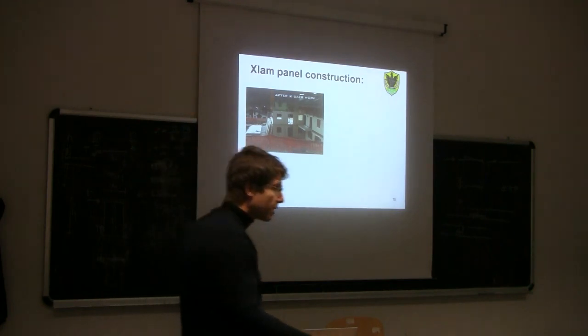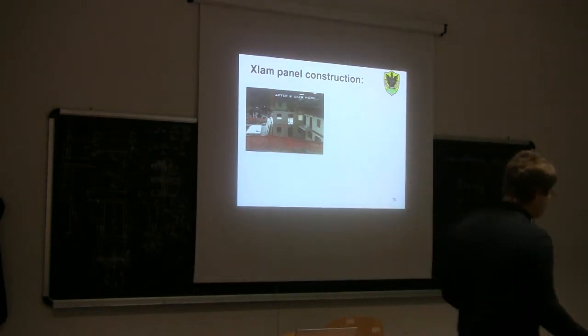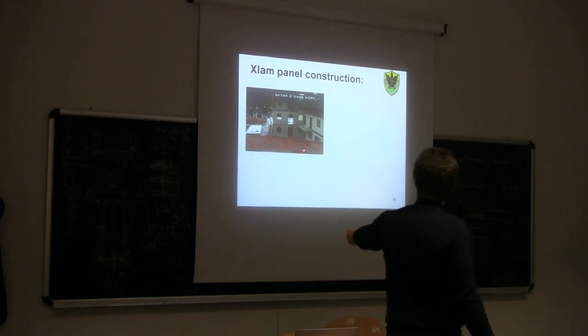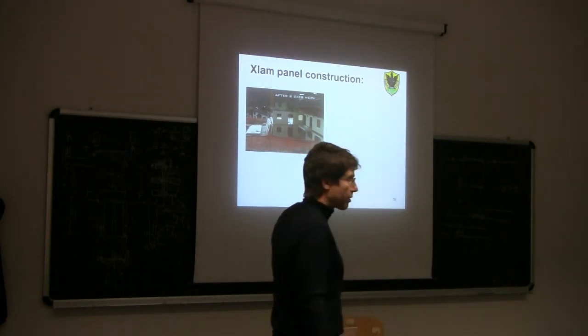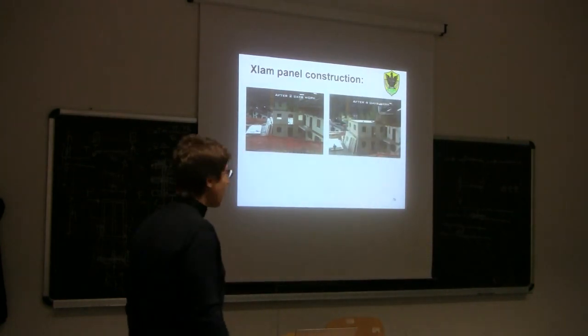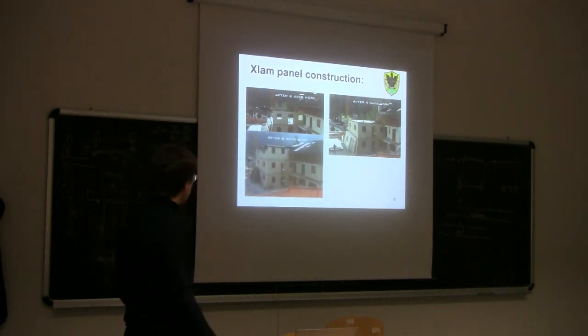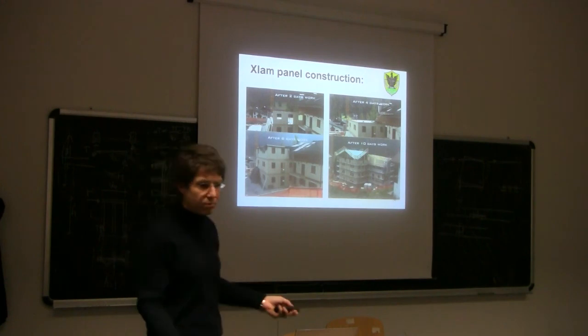With the normal system, even if you do an extension out of reinforced concrete, we were talking about 3 floors, that would be impossible. So one of the reasons why he chose the cross-lam system was this, because as you can see, in terms of timing we are very fast. To construct the first floor, 2 days of work. Then to construct the second one, another 2 days. Then the third one, another 2 days. And in the end, to get to the roof, 10 days.